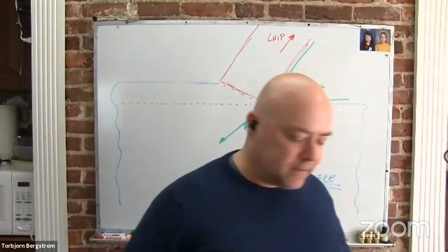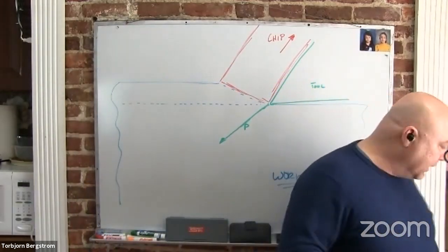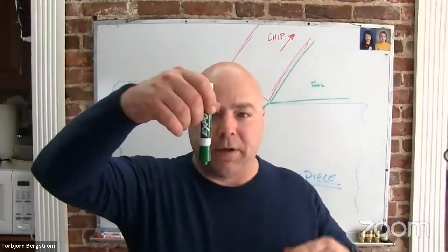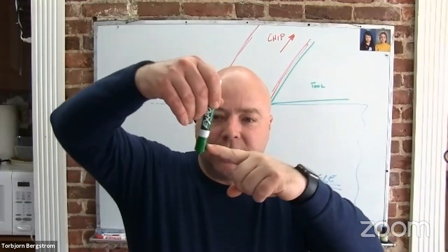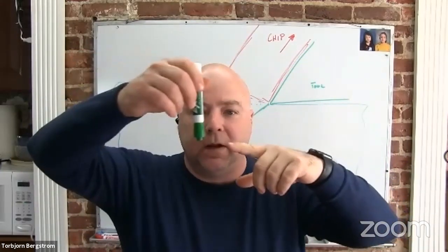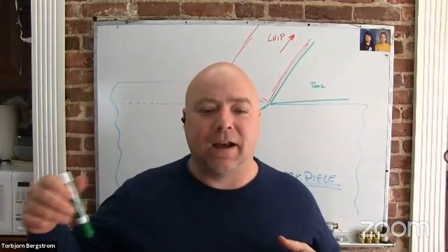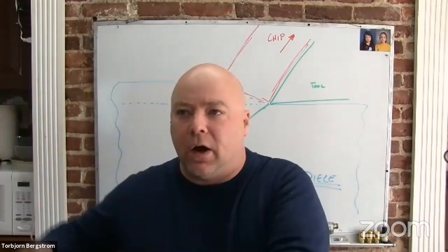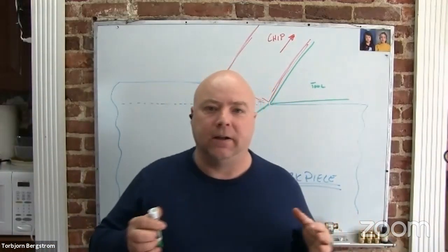Both actually. It's kind of amazing, because these carbide end mills, you'd think that they're pretty rigid, but as the end mill is moving through the workpiece material, there's a force on it pushing sideways, and it bends, and it actually causes the spindle to deflect, and it causes everything to bend a little bit. So the edge of the end mill isn't really where we think it is at any time. Although if the forces are very low, then we probably can't measure the amount that it deflected.